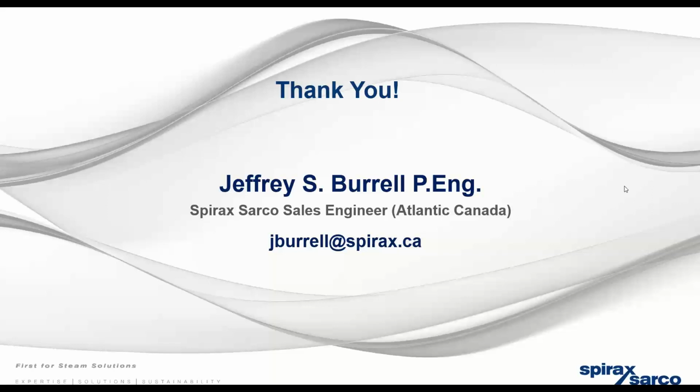The other one I have is how to rectify water hammer in existing systems. Jeff, I know you did talk about separating high pressure condensate and low pressure condensate, or high pressure condensate and pump condensate lines. How do you address that? Because sometimes you have different pressures and there's only one high pressure condensate trap, and you can't really run a completely different line for it.